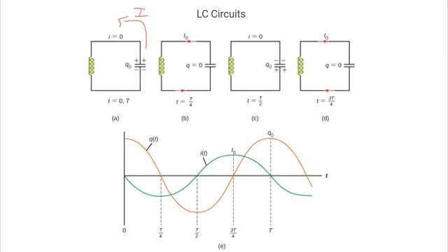When it gets to the maximum amount of current, all of the energy is now essentially in the inductor, because you've taken the energy from the electric field that was stored inside the capacitor, and you have caused this current, caused that energy to now move so that at max current, all that energy is now in the inductor. Then, of course, you end up with continual current in this direction, and you're going to end up with some excess positive charge ending up on this plate.